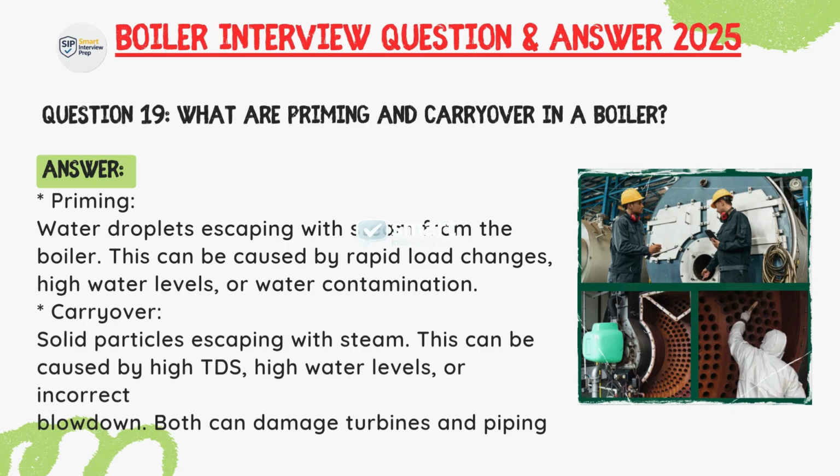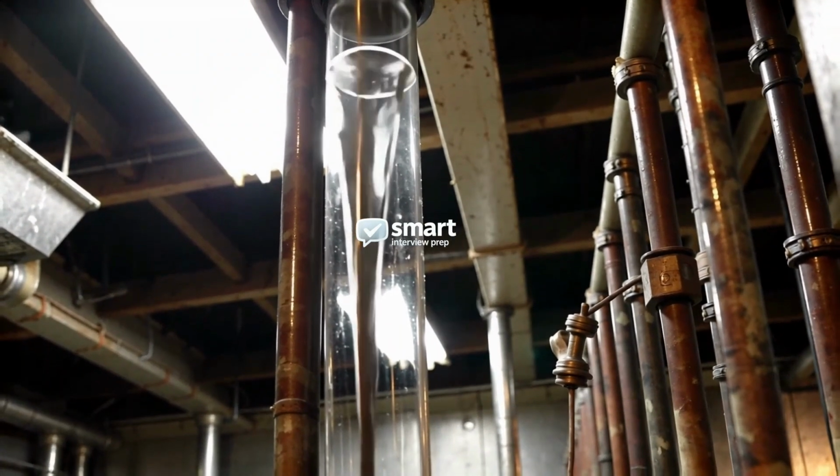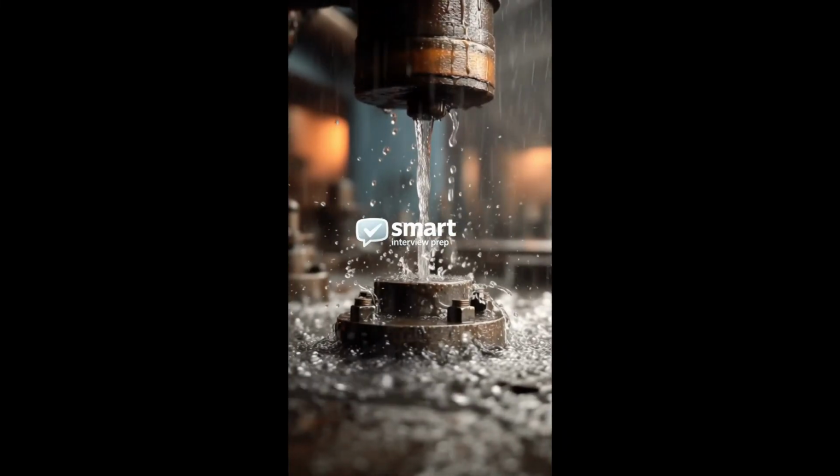Question: What are priming and carryover in a boiler? Answer: Priming: water droplets escaping with steam from the boiler. This can be caused by rapid load changes, high water level, or water contamination.